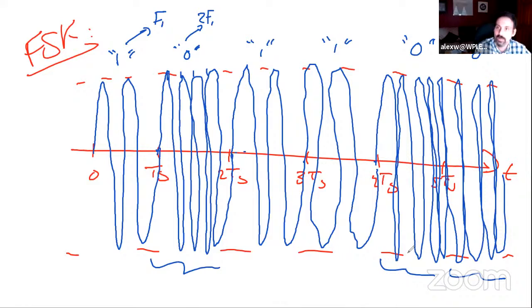And this is like binary FSK. And then on the other hand, we have a 1 and it's half that frequency. So when we look at those, this segment, this segment, this segment, we decode it and say, that's a binary 1 that's been transmitted. So that's the layperson's viewpoint of how FSK works. All the information is contained in what the frequency of that sinusoidal carrier looks like. So that's very important.